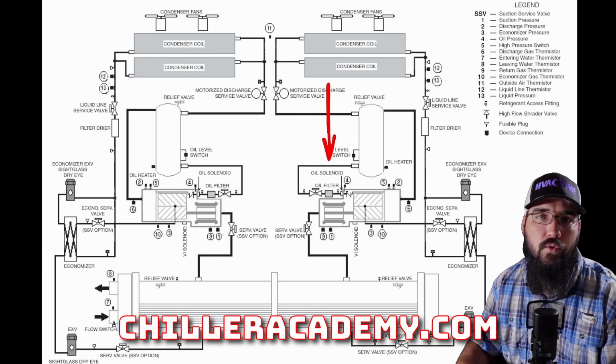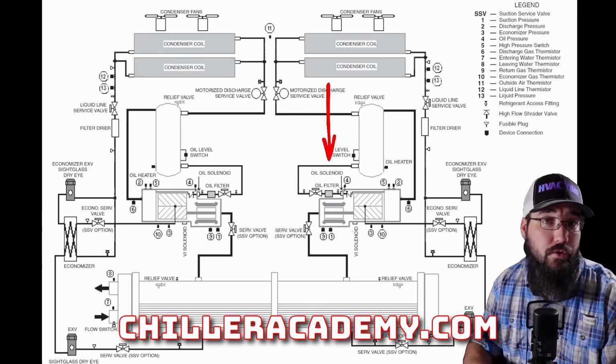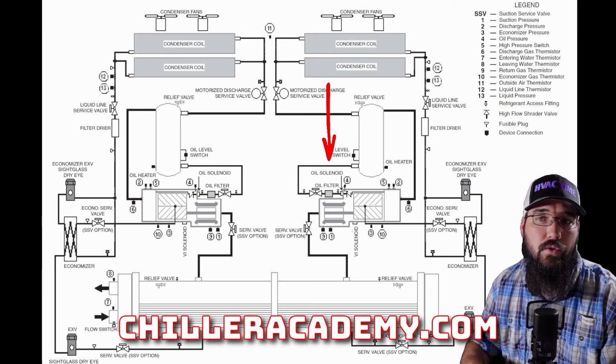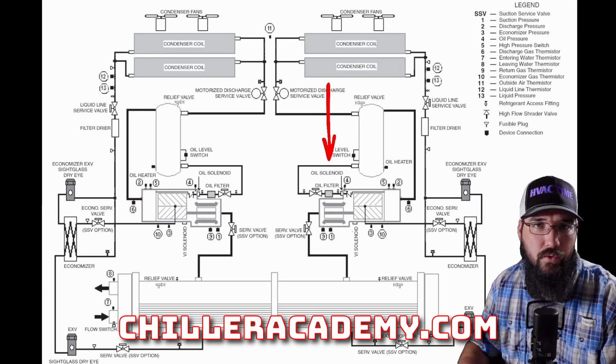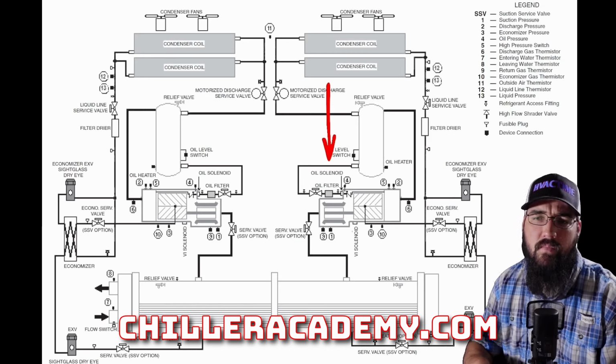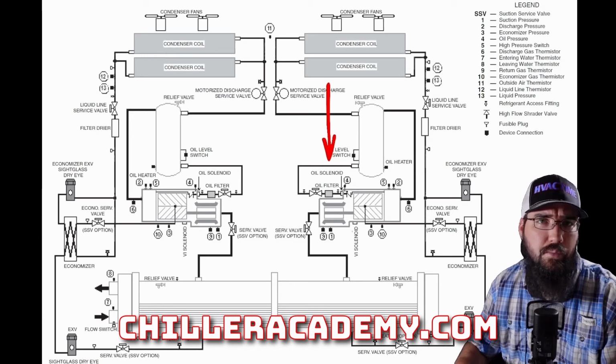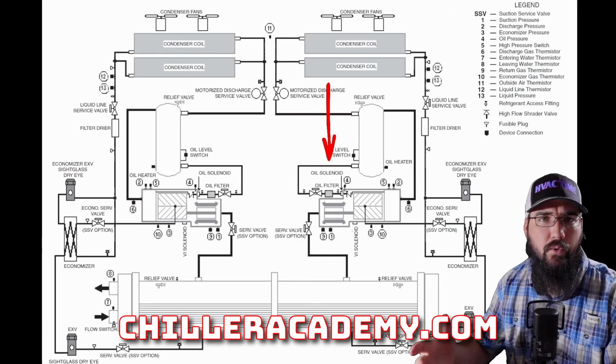Now on the water-cooled side, you'll see them put a larger compressor in, and you'll see them go single compressor, single circuit. But you won't see that on the air-cooled side. It'll almost always be a dual circuit. And I'm not aware of any that run more than 4 compressors total once you get to the largest sizes. So 3 to 4 is going to be the top end.